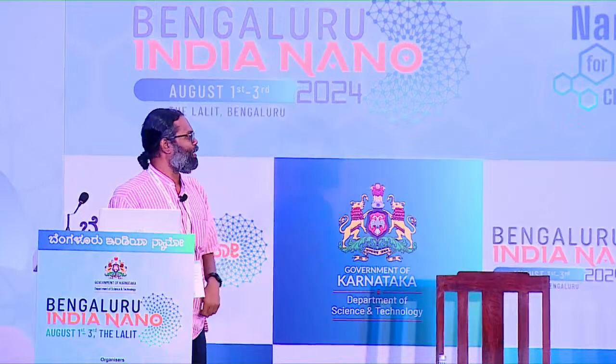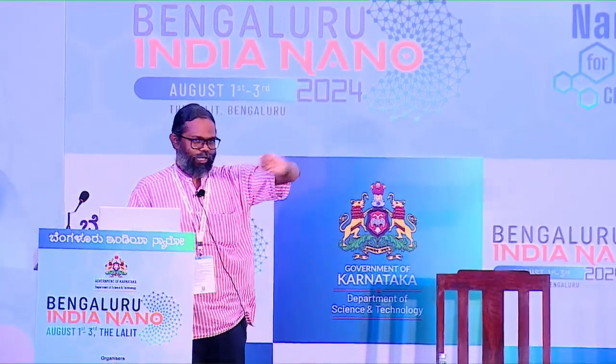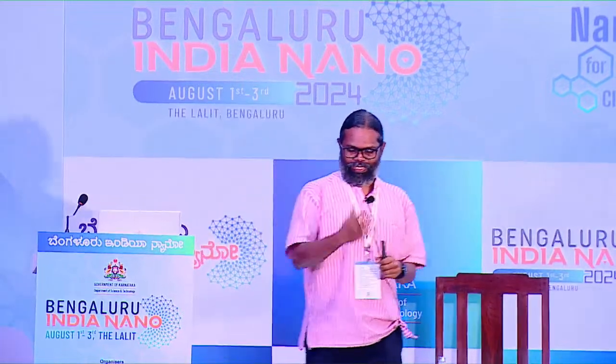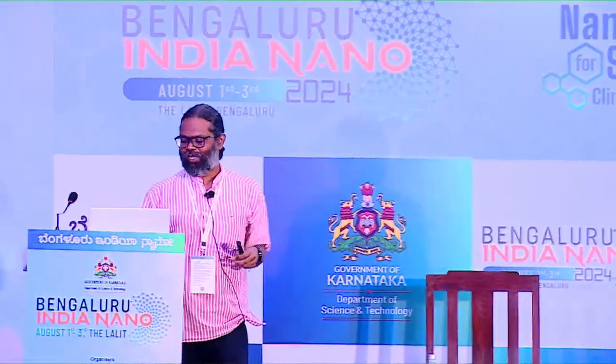The way that we do that is we take silicon and then we deposit a very thin layer of this silica, all right, by using dry oxidation. That means I heat up the silicon and then pass oxygen. So oxygen likes silicon and they react and they form silicon dioxide. And this silicon dioxide is insulating. But this is not the insulator that we want. It is just to protect the top layer.